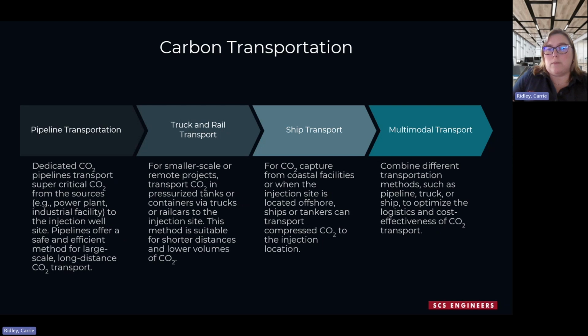For smaller scale projects such as pilot projects or demo scale projects, trucks or rail transportation may move smaller volumes effectively, with the CO2 stored in compression tanks that could be carried on existing rail or highway infrastructure. Ship and barge transportation can be economical along coastal or intercoastal areas or along navigable rivers such as the Columbia, St. Lawrence, or the Mississippi. Of course, nearly any facility would need a combination of transportation types to connect all sources to sink locations.